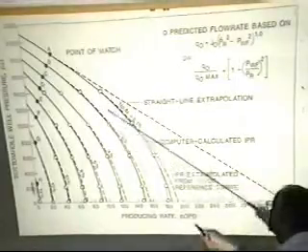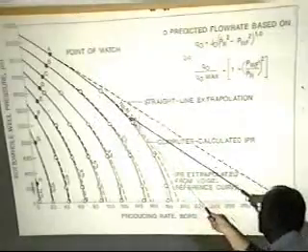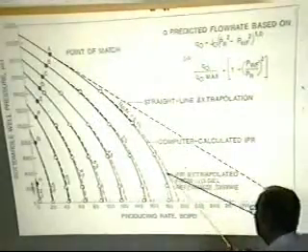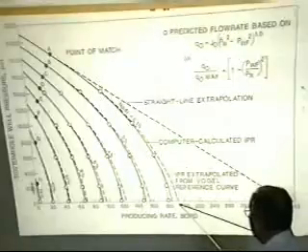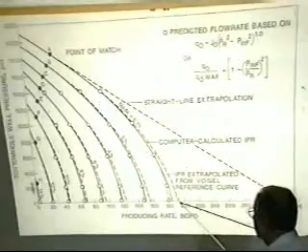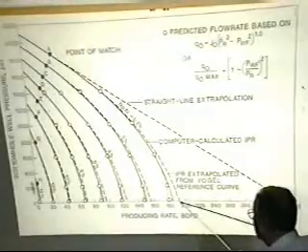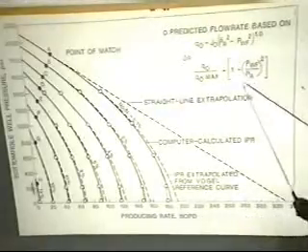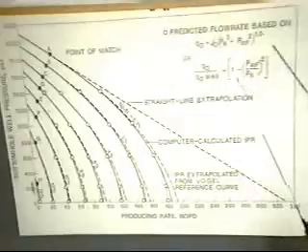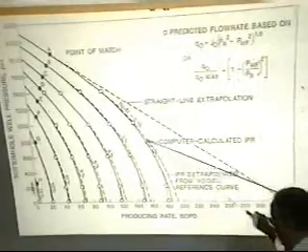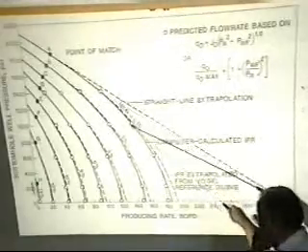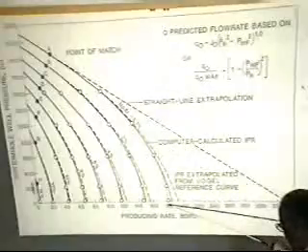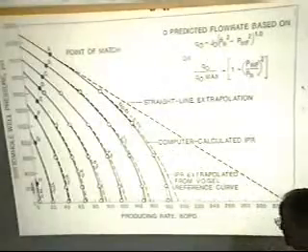If you take his inflow performance equation, which is a dotted line here, the absolute open flow potential of that well is about 195 barrels of oil per day. Now, if you take this form of equation and use it, you'd get the circles, and that shows that you would get slightly less.